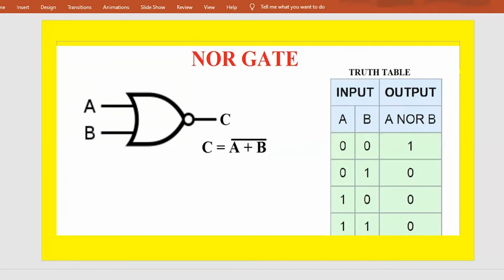So the NOR gate has the property of functional completeness, which it shares with the NAND gate. That is, any other logical function like AND, OR, etc. can be implemented using only NOR gates. An entire processor can be created using NOR gates alone. As NAND gates are also functionally complete, if no specific NOR gates are available, one can be made from NAND gates using NAND logic.